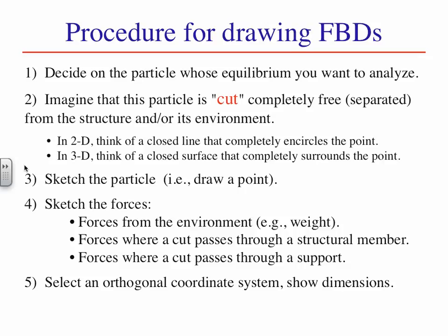Forces that are not included in the free body diagram are those that are actually interior to the enveloping surface. That is, if we have internal forces that are acting between members of an assembly that are not actually cut through as part of the isolation process, we don't include those forces. As you are drawing your free body diagram, make a note of which forces are known, a weight for example, and which are yet to be determined, and give each currently unknown force its own unique symbol.